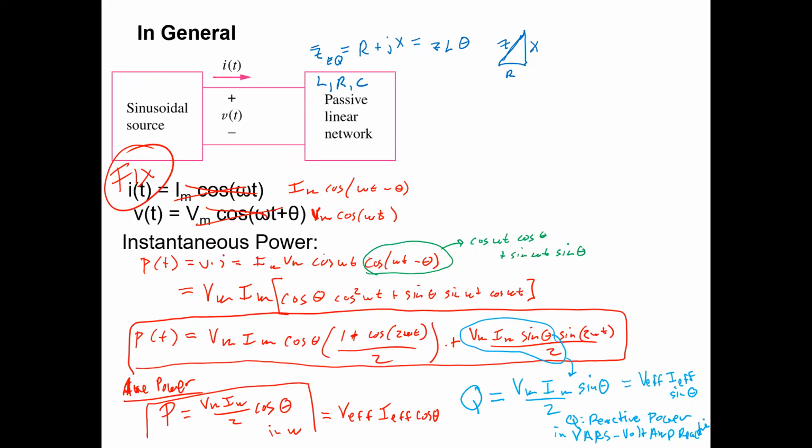We got that circled there. This is the average power, and this is the actual stuff that we can get work out of, whether it's heating up a room or moving clothes around in your dryer. That's what the average power is being used for. The reactive power isn't doing anything for us. It's just temporarily being stored and released into the circuit, but we do need to track that.